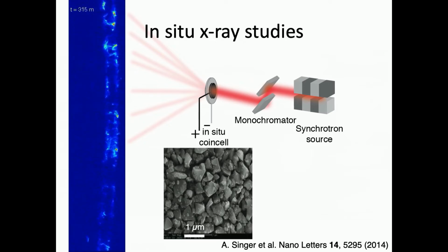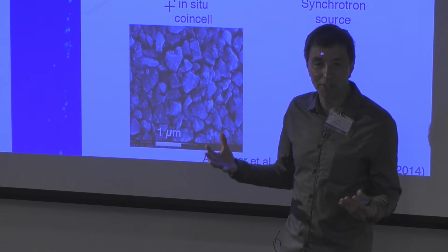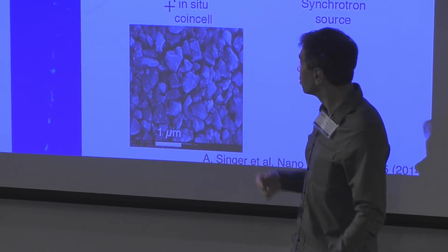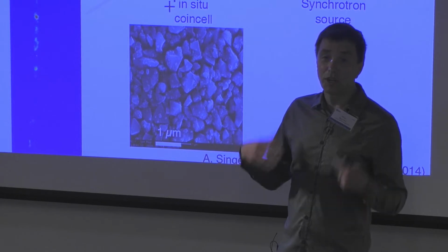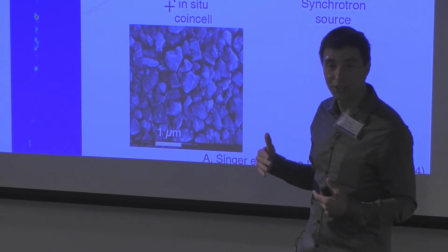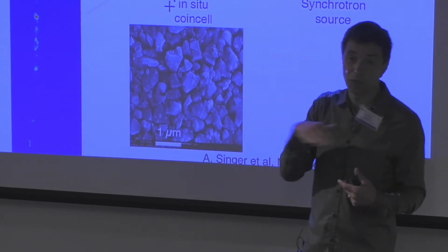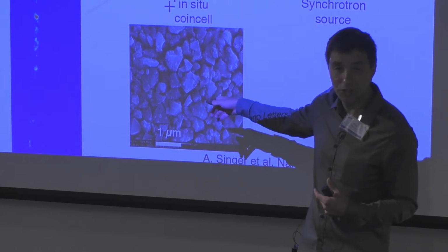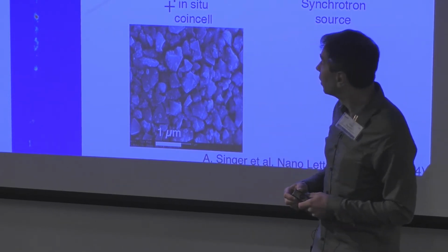There is this phase transition, and let me just tell you that the phase transition is what materials scientists like to avoid, because it's kind of a catastrophic thing if you're a particle, right? You have to undergo a sudden phase transition, which could create cracks and a lot of strain. It's one of the reasons why, if you own one of those electric vehicles, you should not discharge your battery completely. A lot of times they artificially put a limit, so you don't go through the phase transition, which usually happens on one side of the charge-discharge curve.